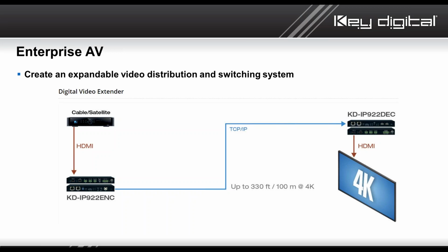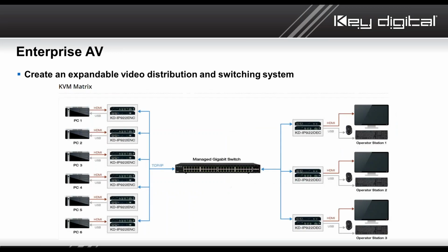So you may wonder, well, if I'm just doing this for HDMI, why would I do that? You look at the distance, it's pretty good, 100 meters, 4K. That's very good, actually. However, with a network switch in line, you would get double: 100 meters into the network switch, another 100 meters out of the network switch, sending all of that connectivity.